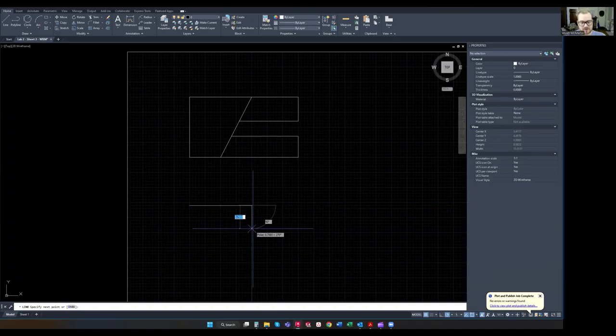Drag it, snap it so it's straight down at 90 degrees and type 0.5, enter. Snap it at 0 degrees, drag it out to the right, and this is going to be 1.5, enter. You can even check before you click escape on your line that you are lined up perfectly with the right side of the top view.